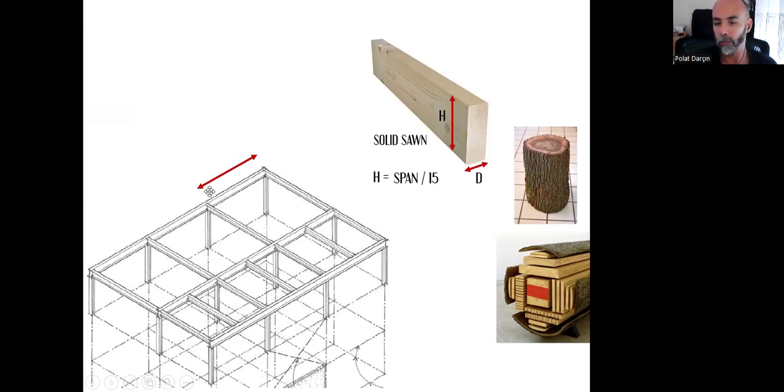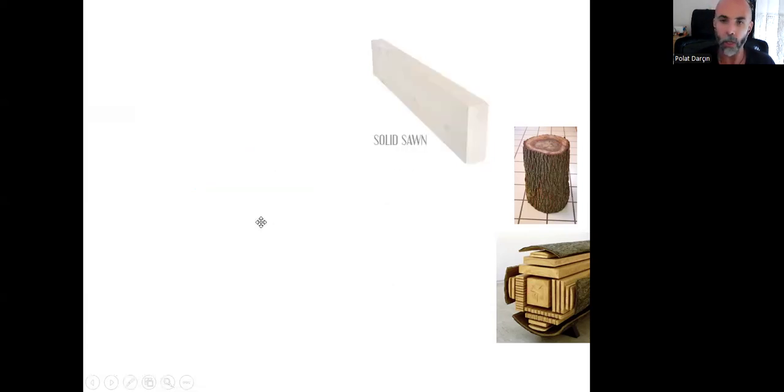We get the span, and we can divide the span by 15, and we can find the necessary beam height for us. And D can be one third or half of the H. So these are some formulas that you can use during your school projects.